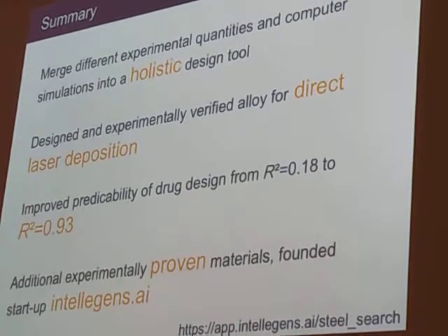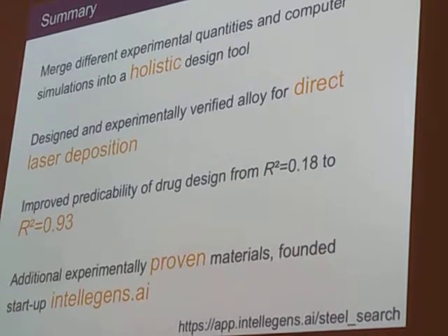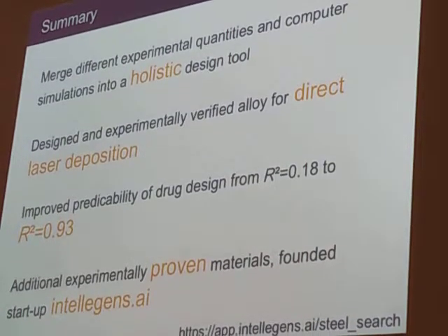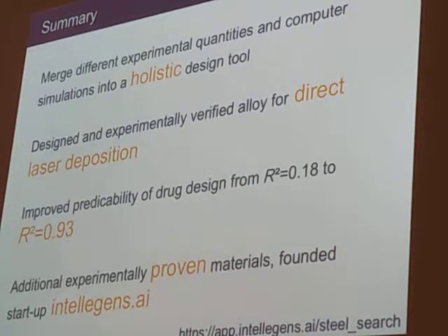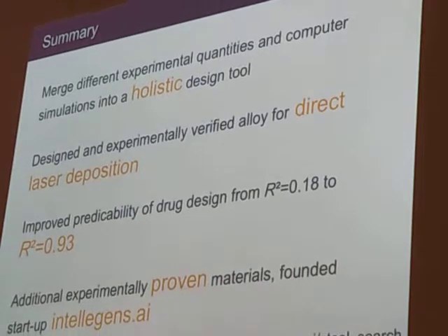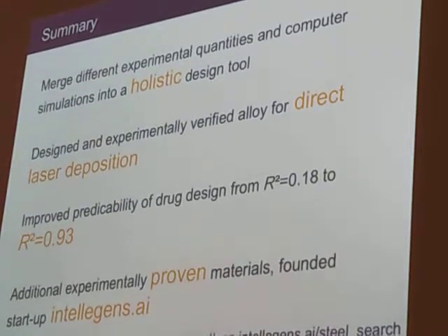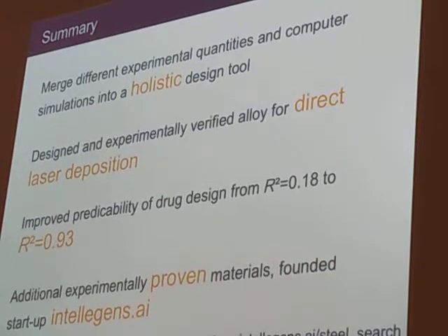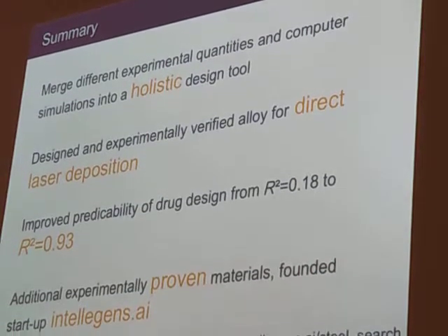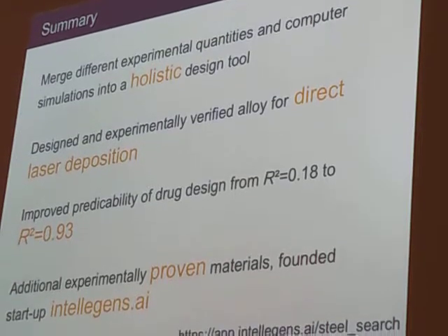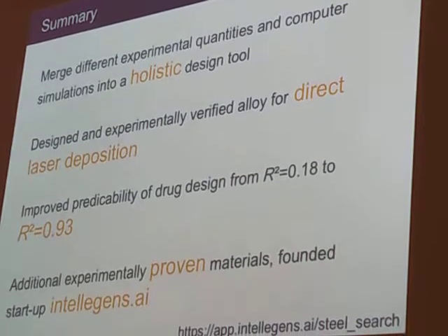If you said 25% gamma prime, this is an alloy which is for sheet rolling, and so evidently this alloy will be very good for welding also. The welding problems come down with 50, 60, 70% in volume for gamma prime. Yeah. So what is new there? Because this is an alloy which will anyway work for welding, no problem. We know that. But what is new with your approach?